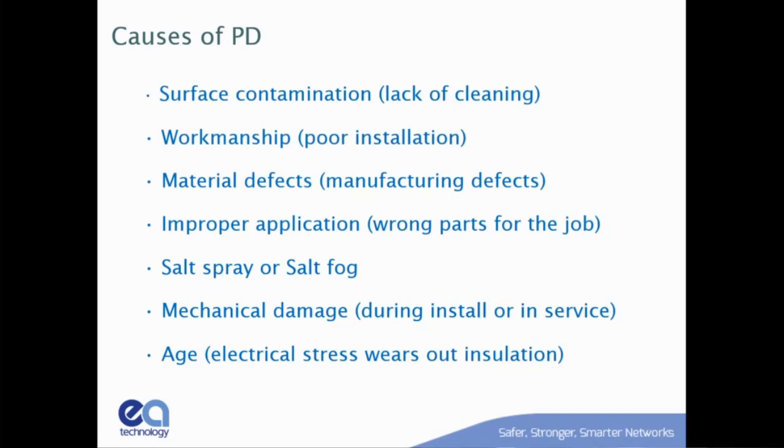In cables, the rubber insulations are better than the XLPE. The very old XLPE was real bad. About 25 years ago, they came out with tree resistant, and tree resistant is PD resistant XLPE. The old paper cables have a lot of PD, but they can also withstand a lot of PD. They all have different characteristics, some pluses, some minuses, but the most common place we find partial discharge is cable terminations. And that can lead to failure pretty quickly.